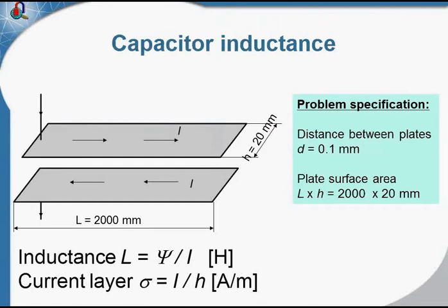The capacitor inductance. In some applications at high frequency or when the transient voltage process appears, the capacitor inductance plays some significant role. So in this case, we should calculate the inductance of the capacitor.